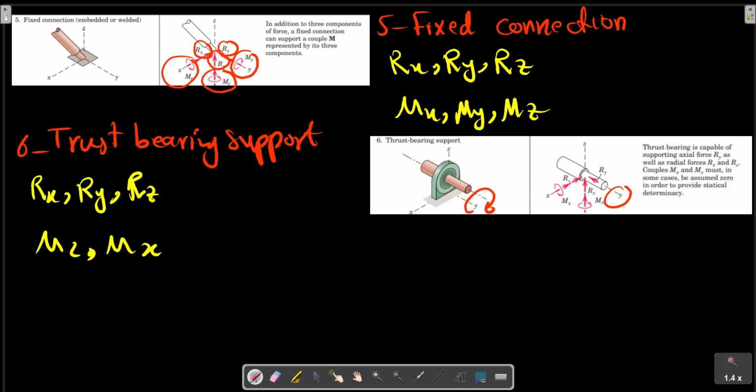If our calculation appears with a minus sign, it says that our arbitrarily chosen direction is not true, and we should reverse the direction of the chosen supporting forces for the free body diagram. The next section is about the categories of equilibrium in three-dimensional cases.